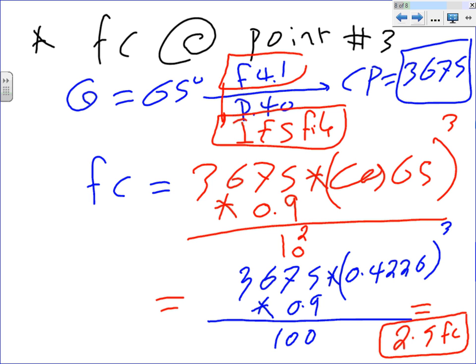Every 2 by 2 feet, it takes a point on a grid, anywhere, vertical or horizontal, and puts a calculation point there. You can make the grid finer, but the more points you calculate, the longer it will take. Inside, I believe the default is 2 by 2. Outside, I can't remember. It's larger if you're doing a parking lot. You can change these defaults too.